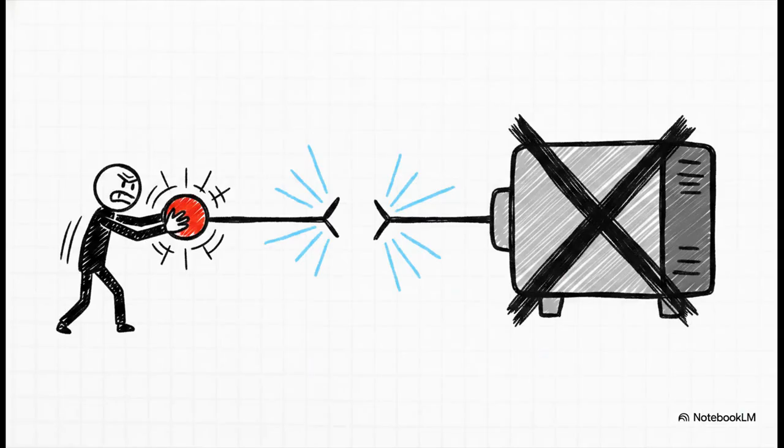Here is another fatal diagnostic trap that catches so many people. What do you think happens if you accidentally use a normally open contact for AR1 in that primary rung instead of a normally closed one? Just think about the engineering physics of the circuit for a second. If it's normally open, power simply cannot pass through it until AR1 is energized, which means your IN1 start button would do absolutely nothing at all. That fatal error prevents the circuit from ever starting in the first place. You absolutely must explicitly understand the difference between NO and NC contacts when you're designing interlocks.